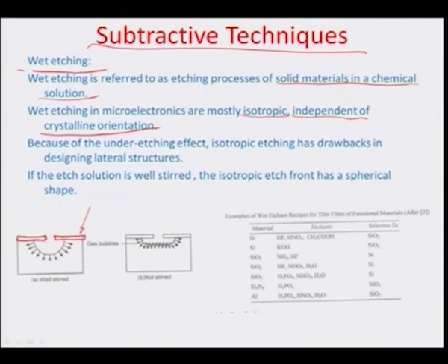What is also important is that there is a rate of etch in the lateral as well as the vertical direction. Lateral etch would let the silicon be cut to a size more than what is intended by the sacrificial mask. This process of extra cutting is also known as undercutting.